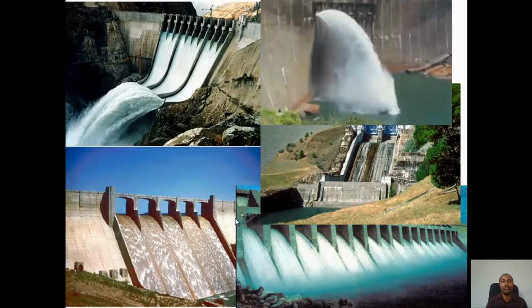Okay, let us see. The first one is an Ogee spillway with a bucket type. The bucket is provided so that it creates trajectory motion in the flow, so that the water hits the river away from the toe of the dam. So this is an Ogee spillway with trajectory action, away from the dam structure.